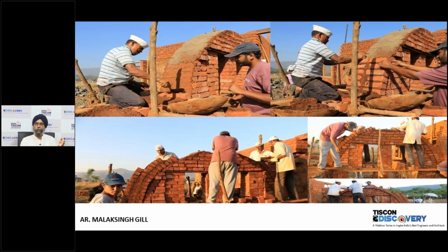So this is an example of how the arches which you saw in this house were built. You can see that it's completely being made with mud mortar. The support system is made first, and then the arch is put on it, and then immediately the support is removed as soon as the arch is loaded. And you will also notice one thing here, that the people working on this are architects and masons and helpers.